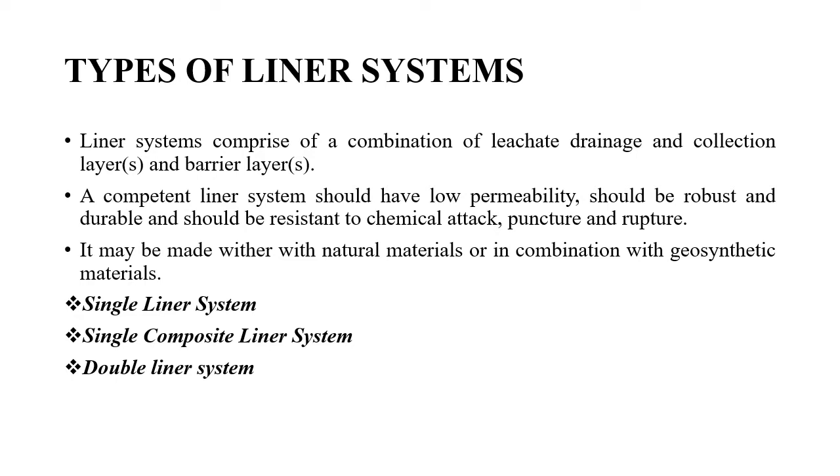Okay, so leachate is the liquid formed out of the waste composite, and this leachate would contain many harmful contaminants or pollutants based on the composition of the waste that you are dumping on the landfill. So in order to prevent the leachate from flowing into the subsoil profile, we need to provide a proper liner system to the bottom as well as the sides of the landfill, depending upon the profile of the landfill.